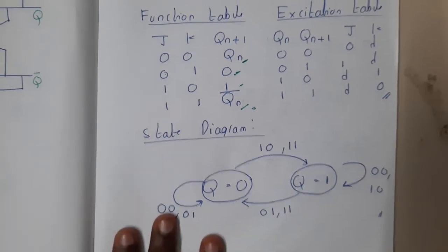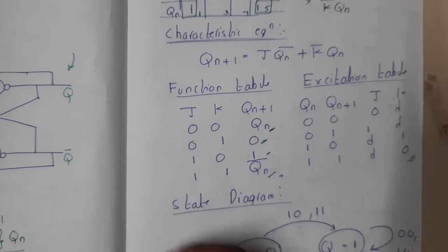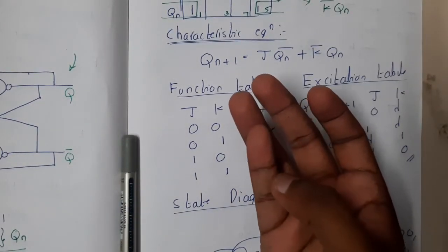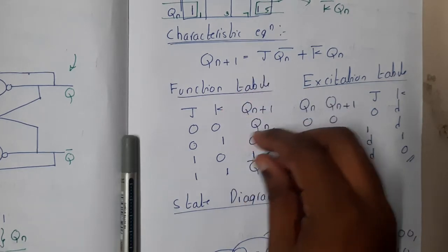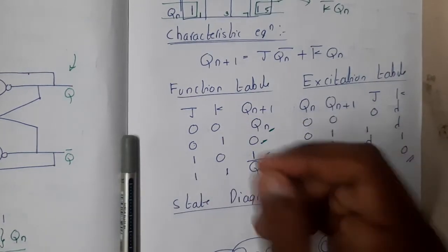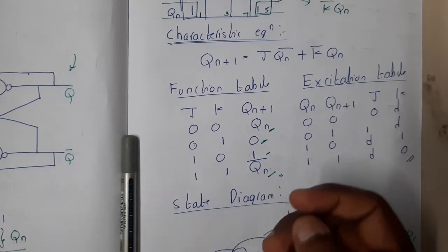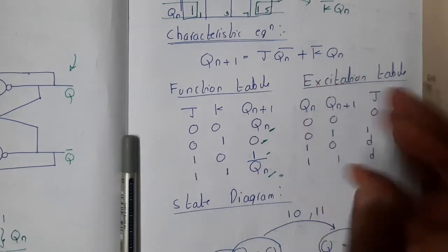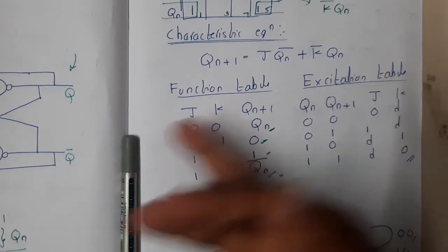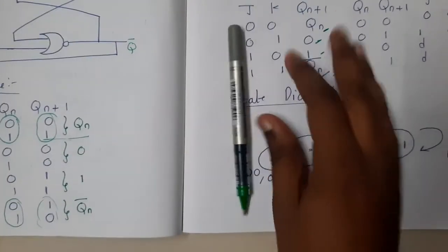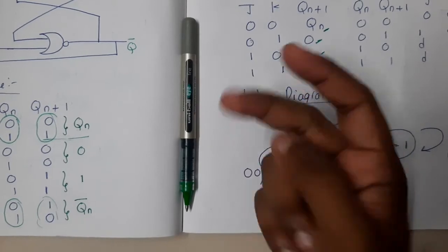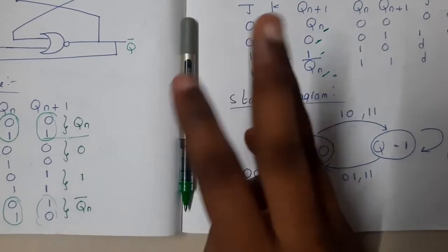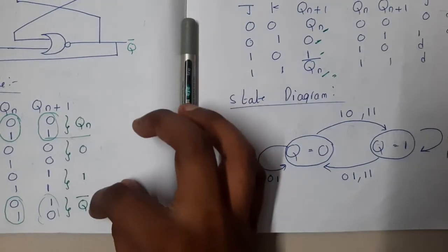You might be saying now: when I covered the SR flip-flop, the reason for introducing the JK flip-flop was that one row was giving an invalid output, which raises some issues. Now you will be saying I told you there are 2 more, the T flip-flop and the D flip-flop. So why T and D flip-flops when this is working perfectly? It is a small flip-flop with 3 inputs, giving 4 different outputs: Qn, 0, 1 and Qn bar.